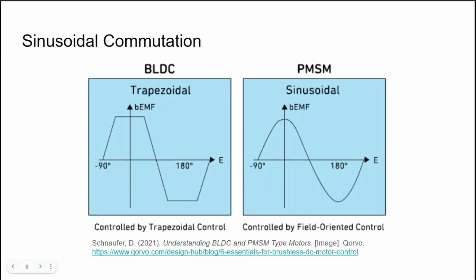So the goal would be to smoothen the power given to the stators. The graph for a 6-step commutation is shown on the left, where we see the power given to a stator at different angles of the rotor. And then on the right is the desired power we want to give to the stators at each angle, which is how we would maximize smoothness and power efficiency. One way to achieve this in practice is to calculate the power to give to the 3 stators at each angle of the rotor. But since there's only so many degrees and the power to give to the rotors is always the same at each degree, a simple lookup table can be used to eliminate the need for doing computations.